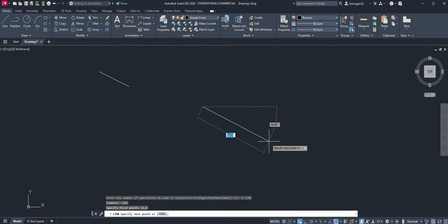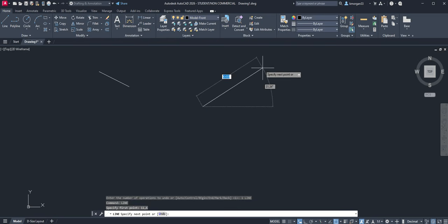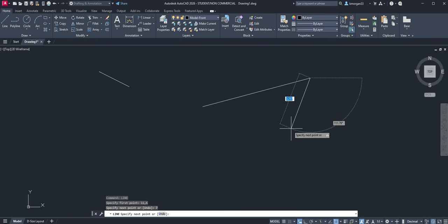Your second point, you can go 26 degrees down or 31 degrees down, or you can say 90 degrees or 0 degrees straight. You can see there's a 3.77 going to 6. That's the distance from the first point to the second. So if I want to go, let's say, 15 degrees relatively, about a distance of 7, I just click OK, and it will go. Of course, you can cut the line with escape. So that's how you input the coordinates.